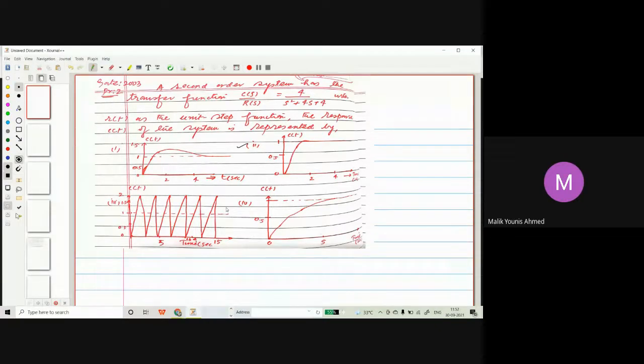Third is not a possibility. Is there a possibility? How do you solve this? Can you solve this? From which do we find out? Roll number 9, I am asking you. From the characteristic equation, you get it. The damping is coming out to be 0.5, so this will be underdamped, so A.